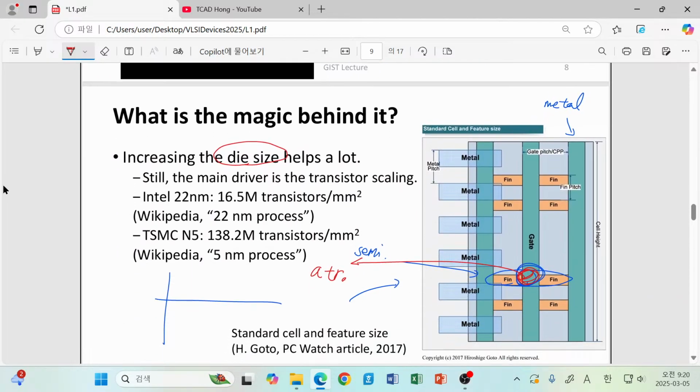That is shown here. So Haswell was fabricated with Intel 22 technology, and this 22 technology is quite an amazing one because that was the very first generation of FinFET technology. Before Intel 22 technology, our transistor was just a planar MOSFET.